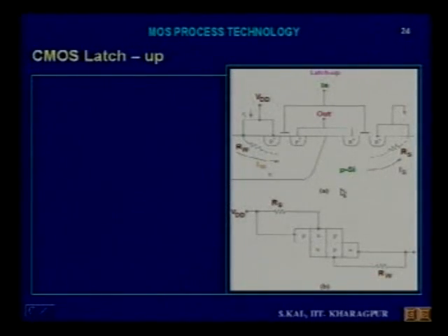Now another transistor will form, which is the NPN. This is the N, and the side is the P, and this is the N. So this is N plus. The P substrate is lightly doped, and this N well region is highly doped. So N, P, and N. Okay, so this is the NPN transistor.